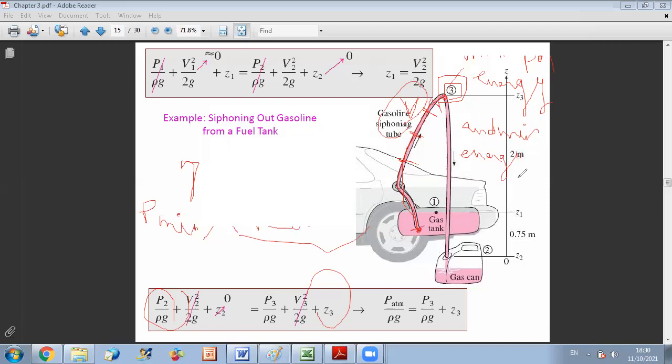And this is what interests me. I should make sure that this pressure is not below the cavitation pressure, to make sure that no cavitation takes place. So this is why we are generally interested in knowing the pressure at this point. If I want to calculate it, I can apply the Bernoulli equation between points 2 and 3, because at point 2 I know the properties. I know the pressure, since my jet is exiting to the atmosphere. So P2 can be replaced by P atmospheric.